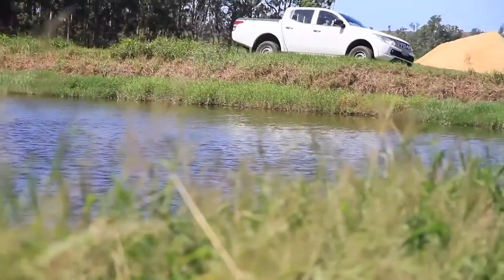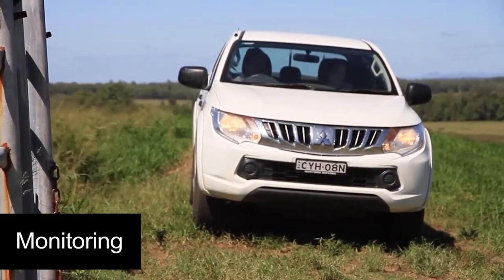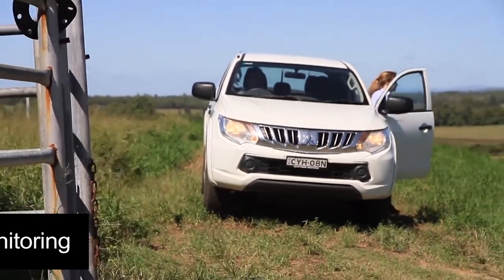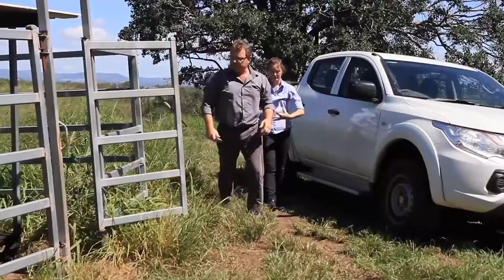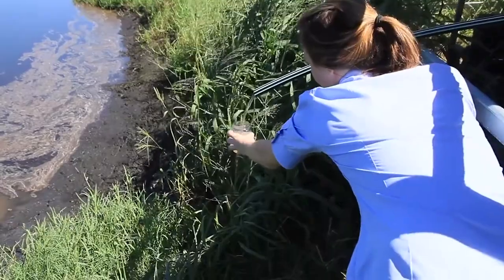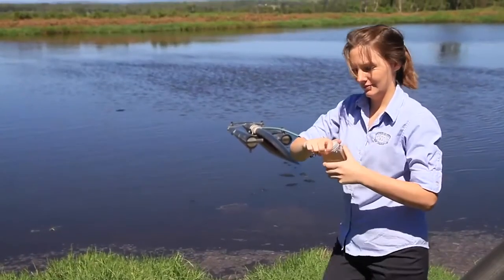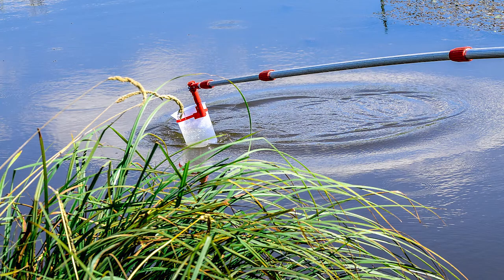Sampling and testing of the discharge of each pond on a regular basis is recommended. Simple grab samples of the incoming anaerobic treated and outgoing aerobic treated effluent are usually representative and reproducible. When sampling aerobic ponds, it is important to collect the sample from the discharging outlet, as samples scooped from the surface of these ponds may not be representative.